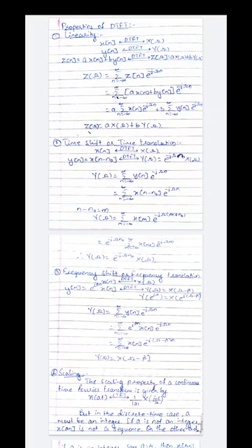If you decompose this exponential, we'll be having two parts. One of the exponential will be e to the power minus j omega into n naught, which is independent of the summation, so it can be taken out. And another exponential along with the remaining terms in the summation, e to the power minus j omega m x of m summation m minus infinity to plus infinity, is the standard discrete time Fourier transform definition.